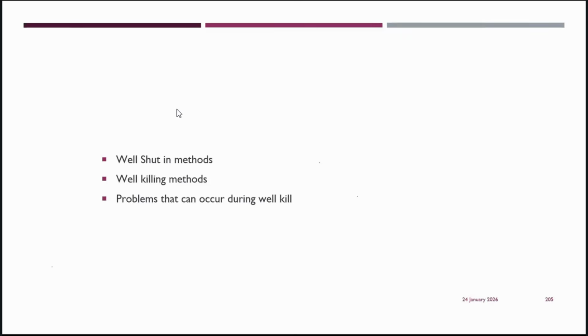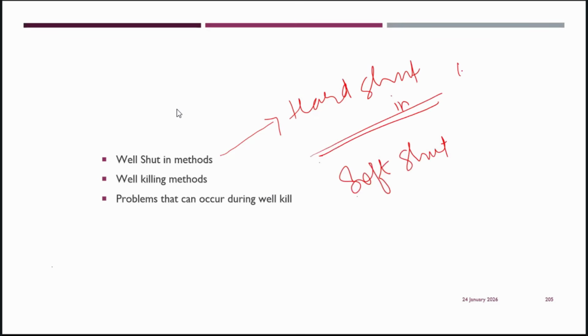So we have seen the shut-in methods. Okay, one shut-in method is hard shut-in, and one is soft shut-in. Hard shut-in closes in just one step. Close the BOP, and your well is closed.